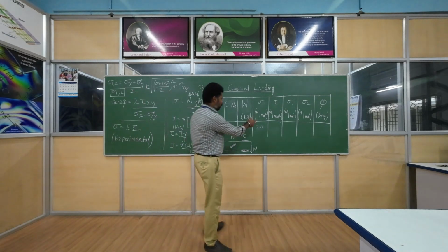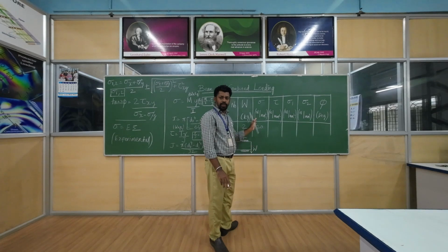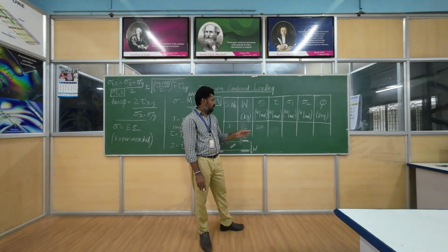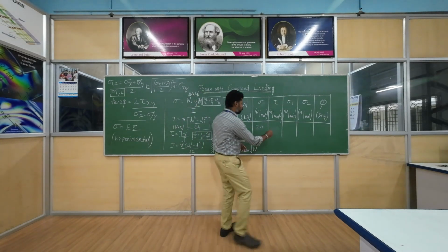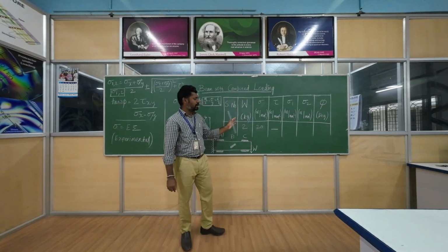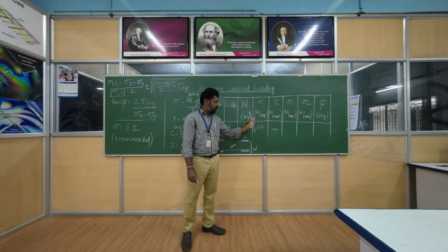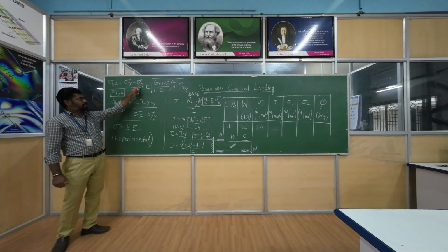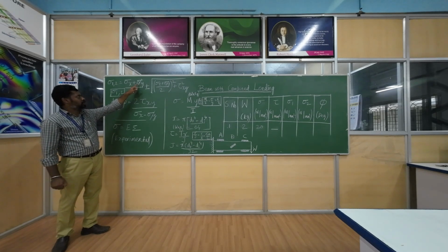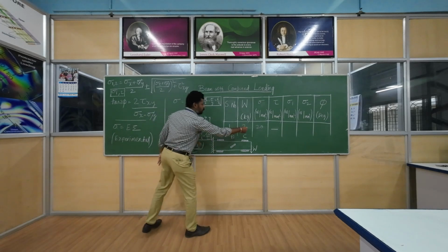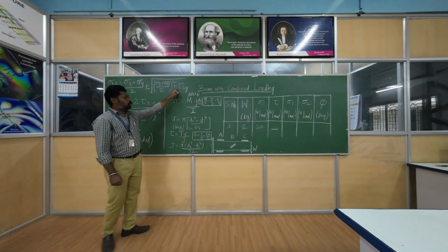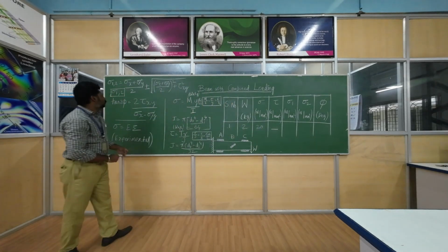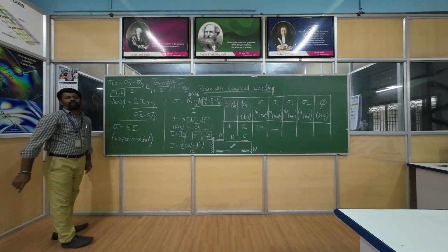So now I have the nominal stress or bending stress from the theory of bending, and also the shear stress using the theory of torsion. Now take these two values and apply them in the principal stress formula. As I mentioned earlier, there is no stress acting in the y direction, so you can ignore that. Sigma x you can take from the bending stress, and tau is what we just computed from the theory of torsion. Just apply here, and you will get the major principal stress and minor principal stress.